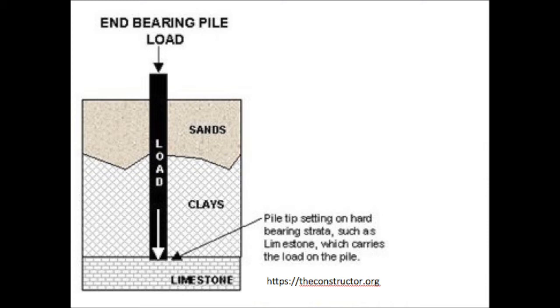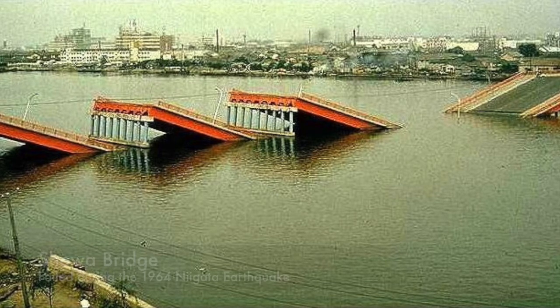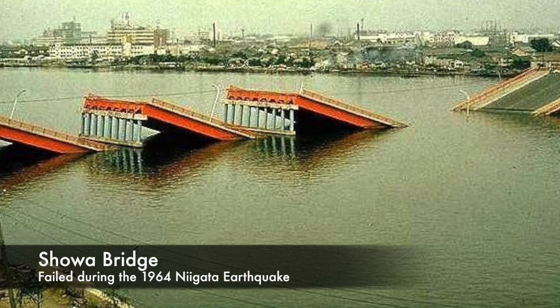The seismic response of pile foundations during an earthquake is very complex. It is controlled by inertial interactions between superstructure and pile foundation, kinematic interaction between foundation, soils, and piles, and the stress-strain behavior of the foundation soil. All these interactions occur simultaneously with ever-changing soil properties as liquefaction occurs. Because of the complexity, many physical and numerical models have been developed in order to fully understand the interaction during liquefaction of soil on a pile.